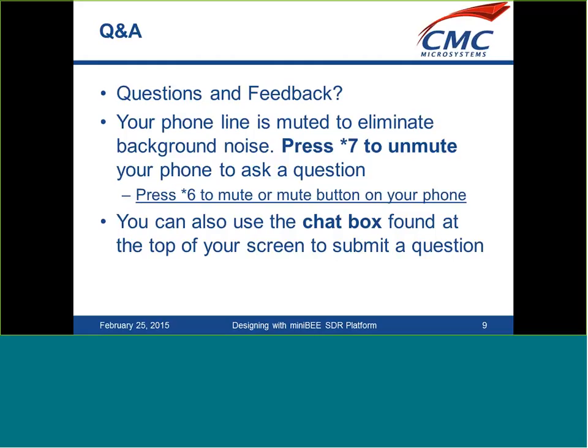You mentioned the local oscillator connecting the two channels, transmit and receive, in the FMC111 card. Is it possible to control those two channels at two different frequencies? Is there a way to control the local oscillator separately for each channel? Yes, there is a command called FMC set LO frequency.